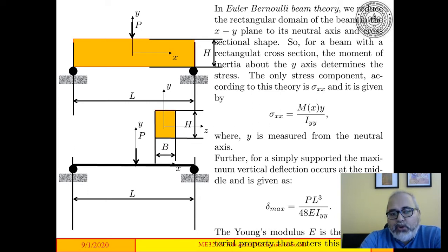So remember what we did in that course. So the actual problem is a beam of this sort. It has a length of L, depth of h, and cross section is h by b. So it's a rectangular cross section. It can be other cross sections also. It's simply supported, and there's a load at the middle. The x and y axis are oriented like this, and from your knowledge of ESO 204, you would know that this x axis coincides with the neutral axis of the beam.